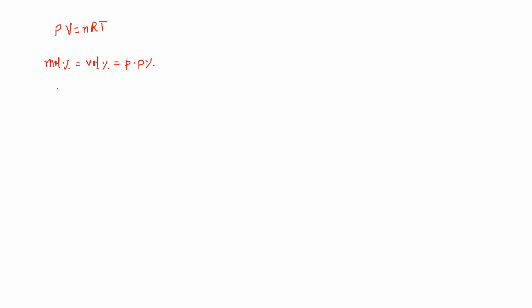In the fourth video, we discussed two very important laws involved in liquid vapor equilibrium. We studied vapor liquid equilibrium and two very important laws involved in it. The first law is Raoult's law, which related partial pressure of a component to its mole fraction in the liquid phase. So this is how we had Raoult's law: Pi equals P naught i times xi, where P naught i is the vapor pressure of the component i.